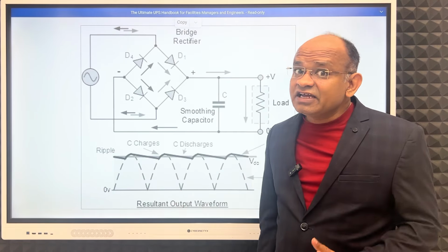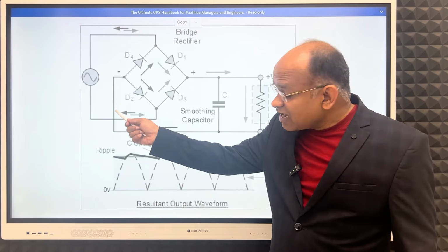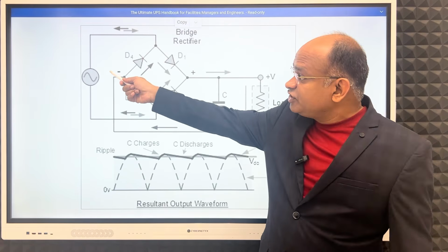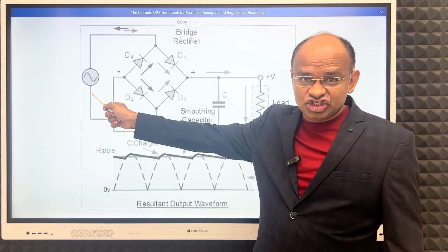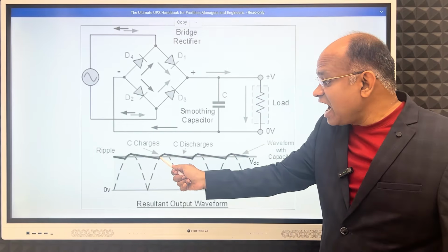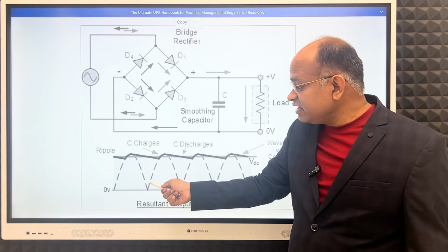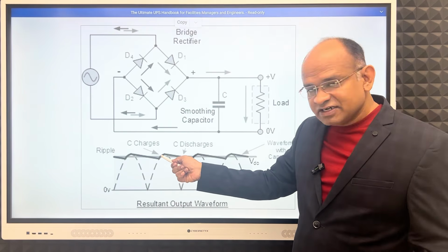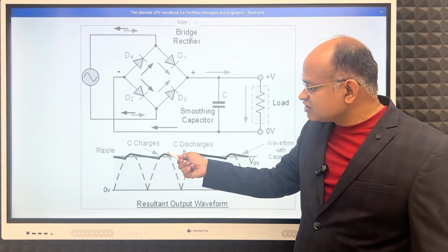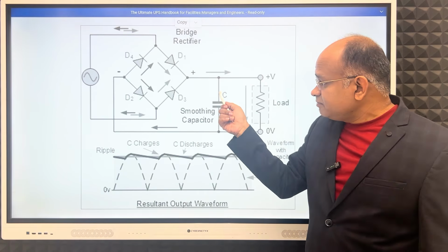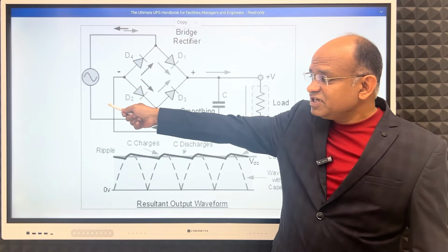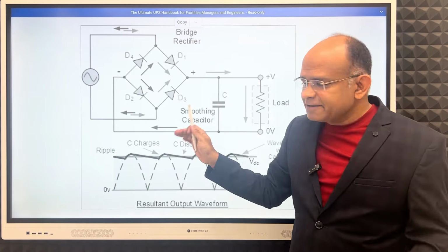Now at this point again what happens? The next half cycle will come into the picture. This is discharging, but here this thing changes. The equation changes here because here again we got high voltage. Till this point it will again charge. The capacitor is charged till this point already, so from here it will again start charging. So again the voltage level will rise because in the second half cycle it will go to peak, right?